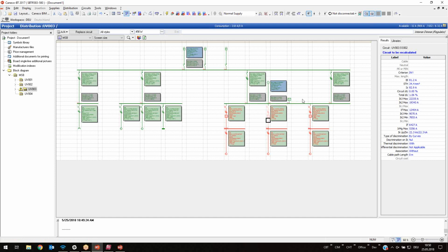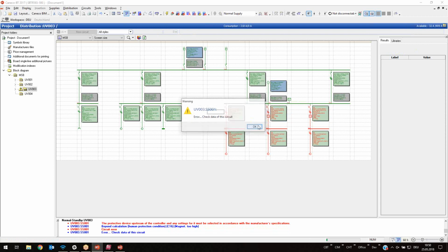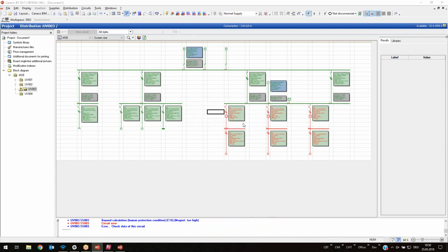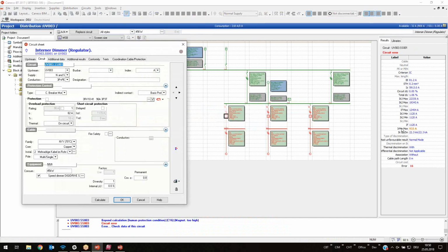The UPS right now. The thing is, it's out of range for the system. I did not calculate it, so maybe, yes, right now it's out of range, you're right. Because we have here a protection device which is tripping at 1170 ampere. But the maximum we can set here is 933 to consider that the protection device can handle the UPS.